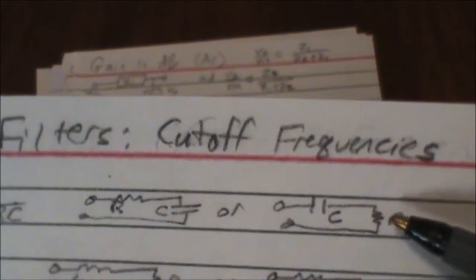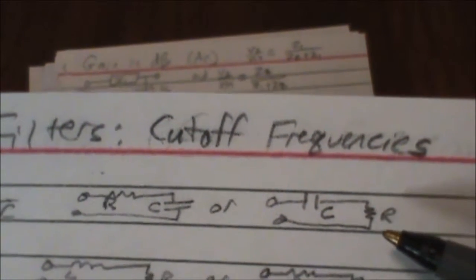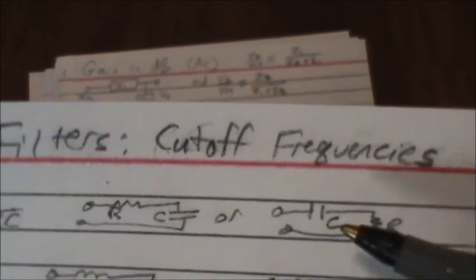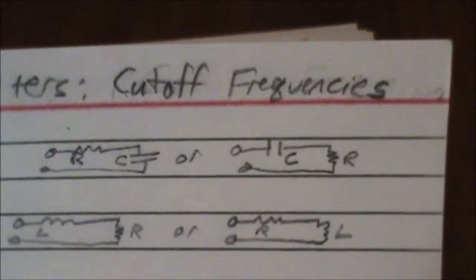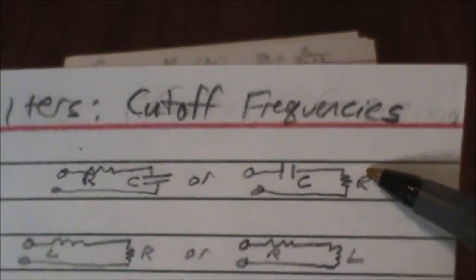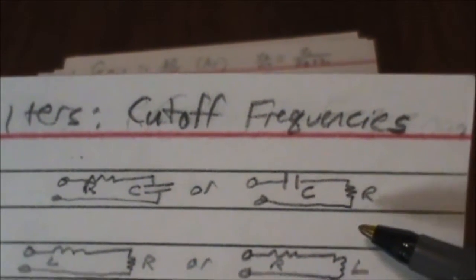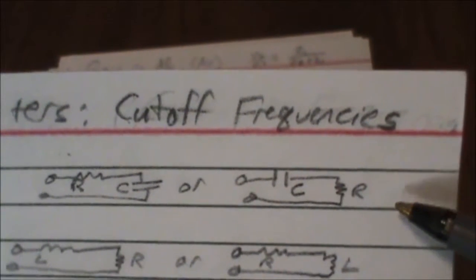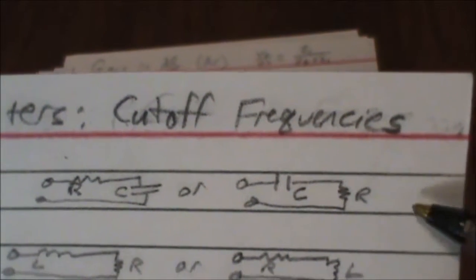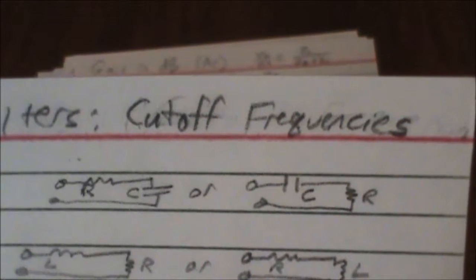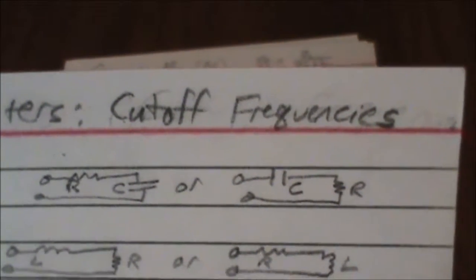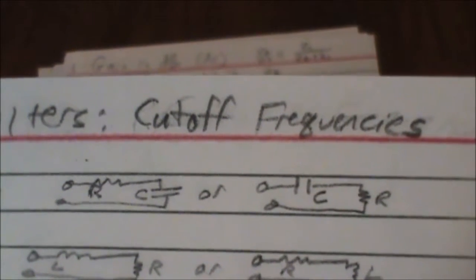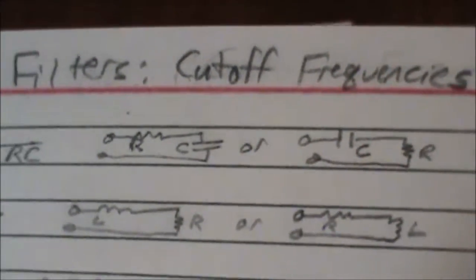So that means, okay, but as the frequency goes up and up and up to exceed our 5 tau, well then current's going to get through. There's going to be this resistor here in parallel with where we're taking a measurement of voltage or feeding the rest of some circuit downstream from this resistor, and it's going to be a high pass filter.